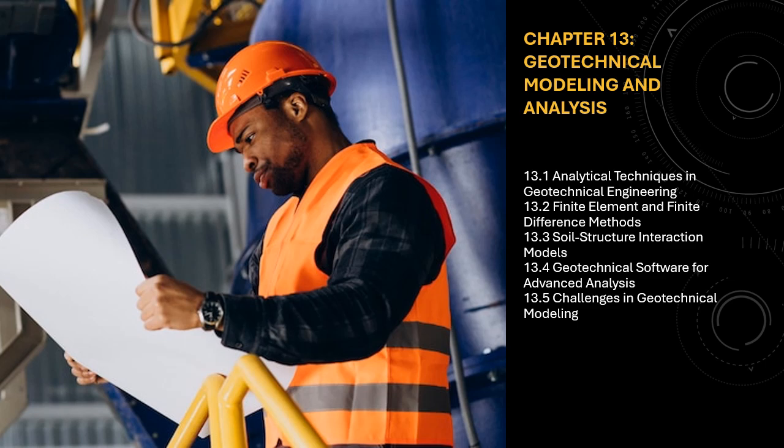13.1.2.2 Finite Difference Method, FDM. The finite difference method is used to approximate the solutions to differential equations governing geotechnical systems, particularly for problems involving time-dependent changes such as consolidation and seepage. FDM is often used in the analysis of seepage through soil masses, soil consolidation over time, and thermal effects on geotechnical structures.